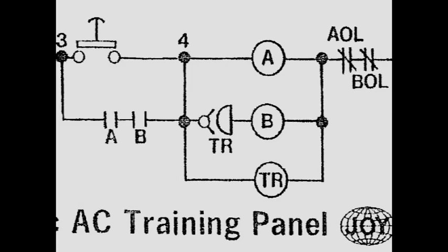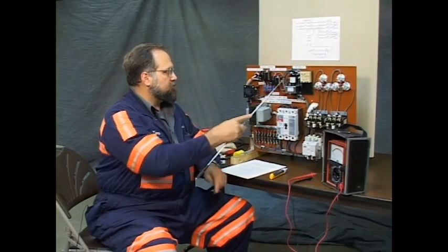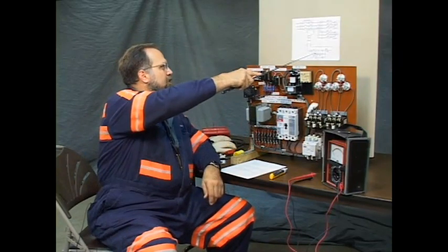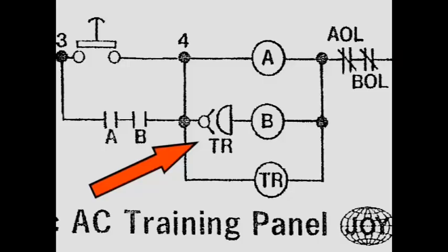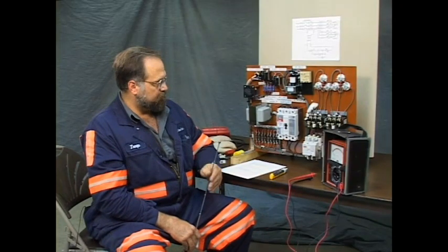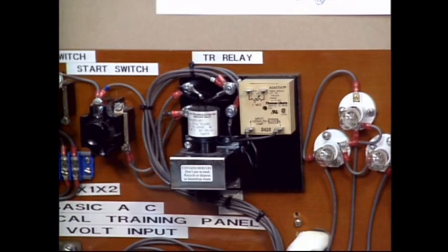TR mercury tube. The TR mercury tube is this component here. By the fact that it's shown with wings, those diagonal lines off one of the points there, not on the bowl but on the other, that symbolizes it is a timed mercury tube. And the timer portion of this is the little beige colored box on the side.